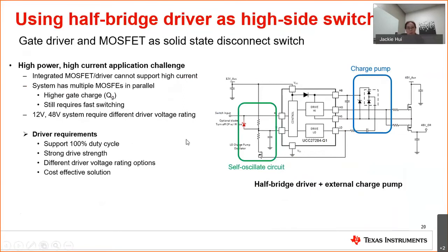So that's why we are getting this request, and because of that, we came up with a simple circuit, basically using simple components to build an external charge pump, which can pair with pretty much any half-bridge driver. You can use it for DC operation, and it can support 100% duty cycle. We will go into explaining how this circuit works, but before we go into that, let's take a look at what's required for this type of driver.